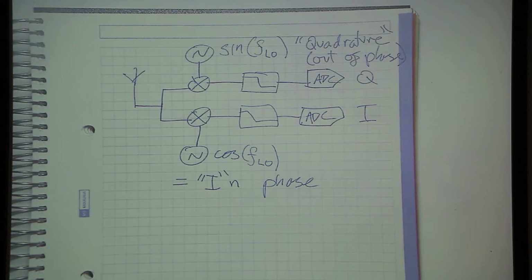What I'm getting at is we need to take this second set of measurements, because otherwise we don't have enough information to work out what our original signal really was. And this is one, and by far the most popular, way of taking that second set of measurements. When we have those measurements, we don't typically draw them as sine waves against time, because for most sorts of data that we might be interested in decoding on the radio, that's not a very useful way of processing it.